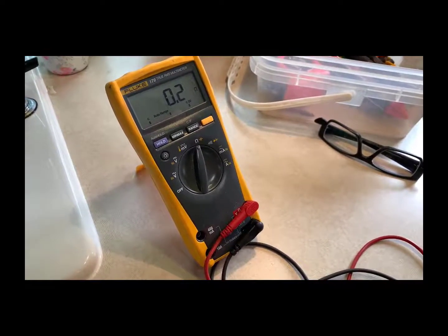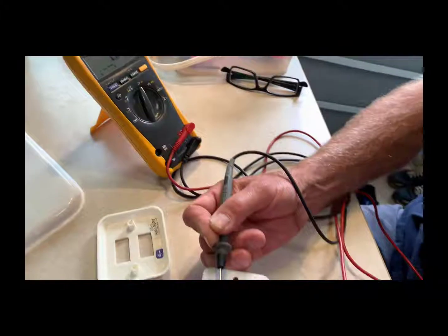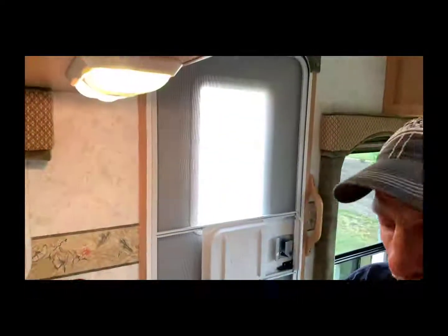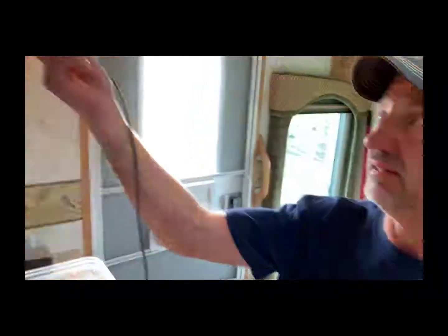So that's one way we can always check switches to see if they're working properly. When we have a switch that's on, it should be a short, and when it's off, it should be an open. One of them allows current flow and enables a load to do work, like a light or a motor or anything like that, or a heater. Or it disables current by providing an open circuit in the off state and turning the device off.